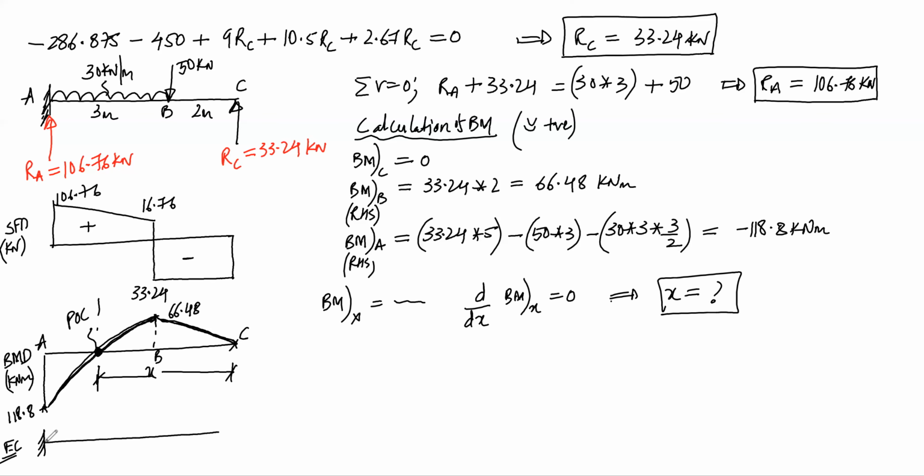You can draw the given beam without the forces. So here in BMD, the downward portion is hogging, the upward side is sagging. So from point A to this point, your beam has to hog like this, and from point of contraflexure till point C, the beam is sagging. So this is your point of contraflexure, and this is the elastic curve.